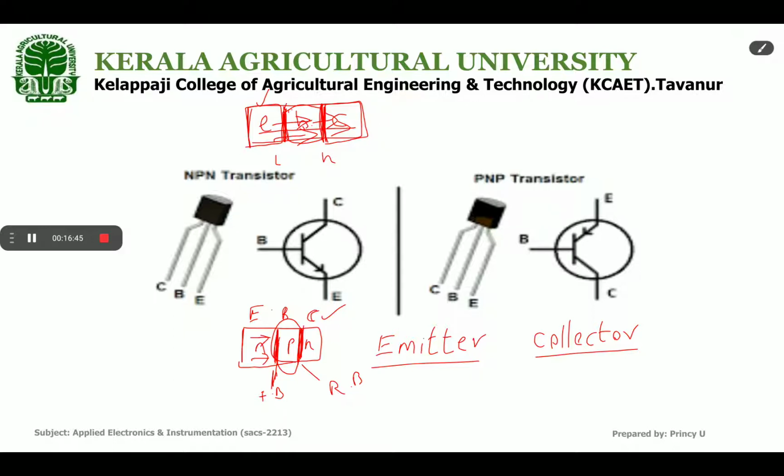Current flows like this in a transistor. So you always remember, emitter is heavily doped, base is lightly doped and very thin, and it passes most of the emitter injected charge carriers to the collector. The collector is moderately doped.